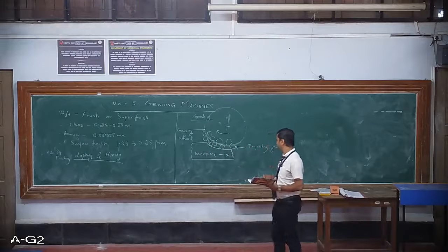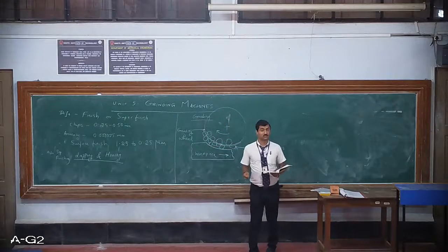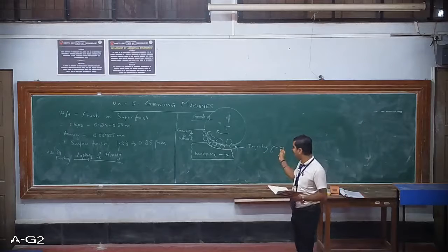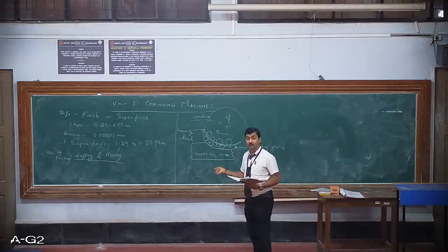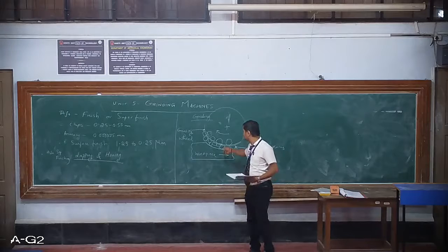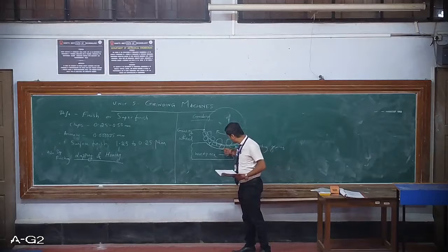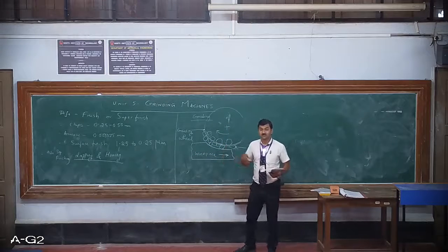That is how it happens. Similarly, here these abrasive particles are stronger than the metal itself, so because of the hardness and sharpness, they will help in removing the material from the workpiece. If you give a rotation clockwise, you can observe that fine particles from the surface are getting eliminated, or chips are formed.